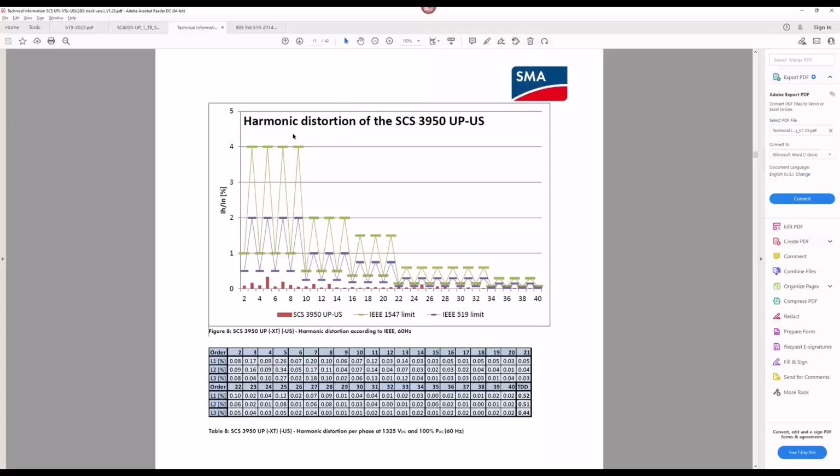However, if you want to be a good citizen, say, hey, because we have this capacitor in our system creating resonance points, our criteria established at the PCC may be different or more stringent than the IEEE standard, right? So that's when you may want to consider modeling more details or more layers of the utility system instead of only using one source, right? A third question, why do we have 33 and 66 in the Excel sheet?